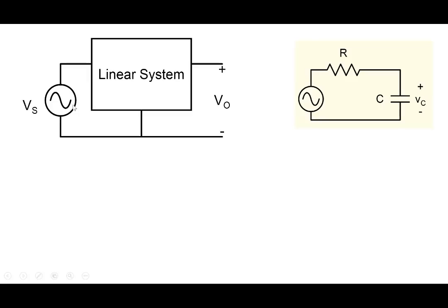What we do is we excite it with the sinusoid and we look at its response as a function of the frequency of the sinusoid. Note that in a linear circuit, the amplitude doesn't really matter. We apply 1 volt and we'll get some output. If I make it 2 volts, the output will also double. If I make it 3, the output will also triple. So the magnitude of this input doesn't really matter. I can put 0.1, I can put 1, anything. Many times the convention is we put it as 1 cos omega t. So the idea is the linear system that you're trying to understand, you can excite it by a sinusoid like this, and then observe the behavior. The output is also going to be a sinusoid.